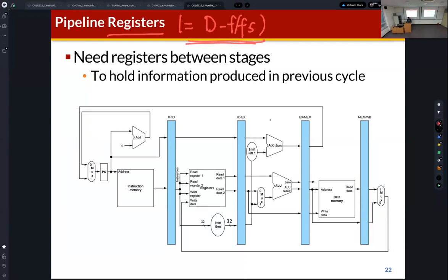When we implement a digital system, these are D flip-flops, the same clock signal is connected to the clock port of the D flip-flops, and between these D flip-flops, we can find combinational logic. So we can understand the pipeline architecture design like this figure.